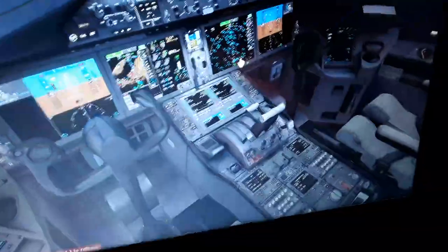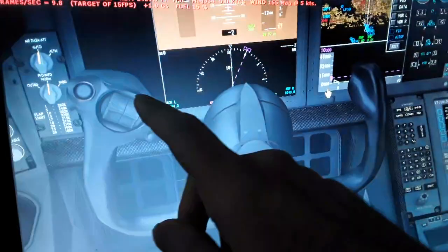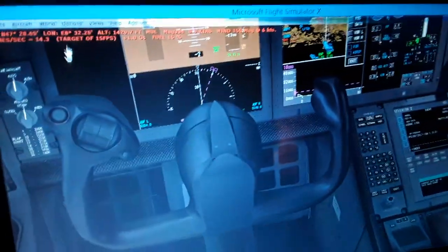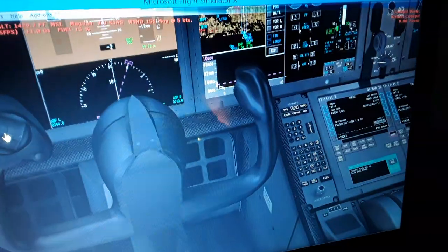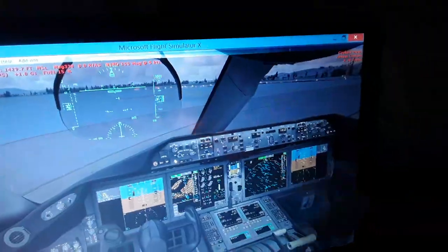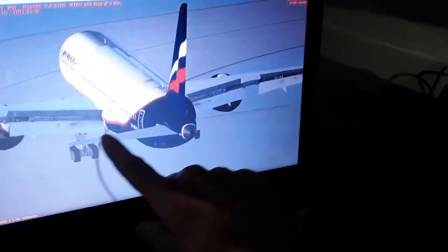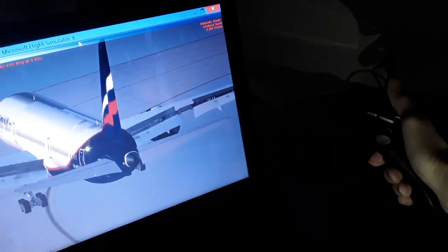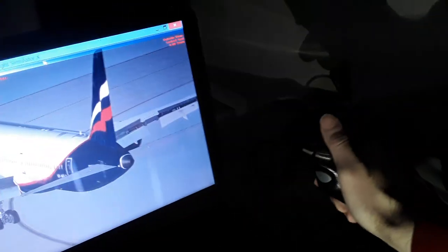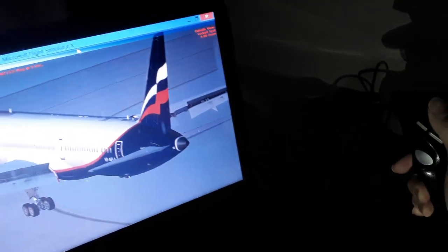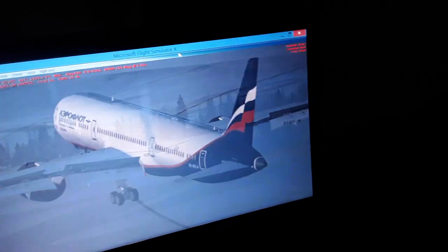Also the autopilot, I will show you the flaps and the speed brakes, the stabilizer trim. So we'll continue with the stabilizer trim over here. We can trim the elevator up, trim the elevator down like this. You can see the elevator, the outside view over here. So we can also climb and descend and also trim the surface, which is a flight control of the aircraft. Also use the rudder, other flight controls, make left and right turns. So I'll talk to you about the aircraft flight controls, how we can use the trim of the elevator also.